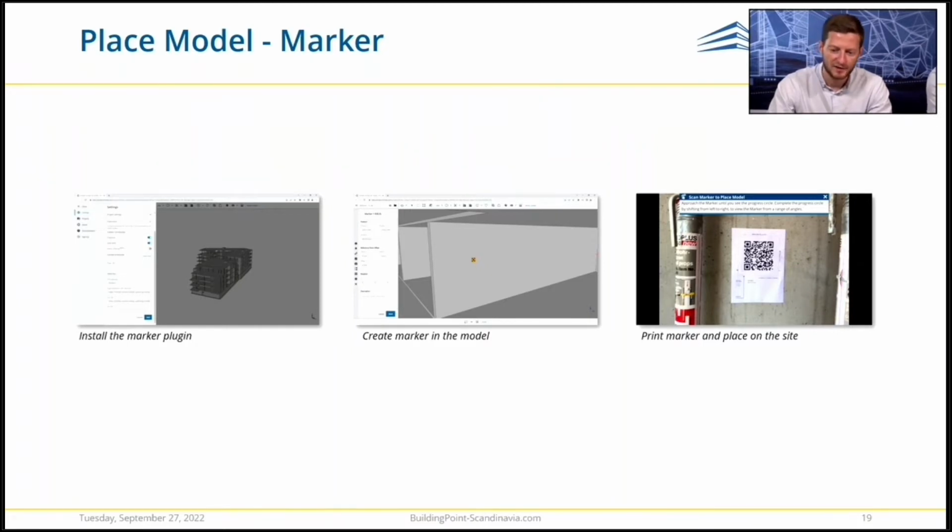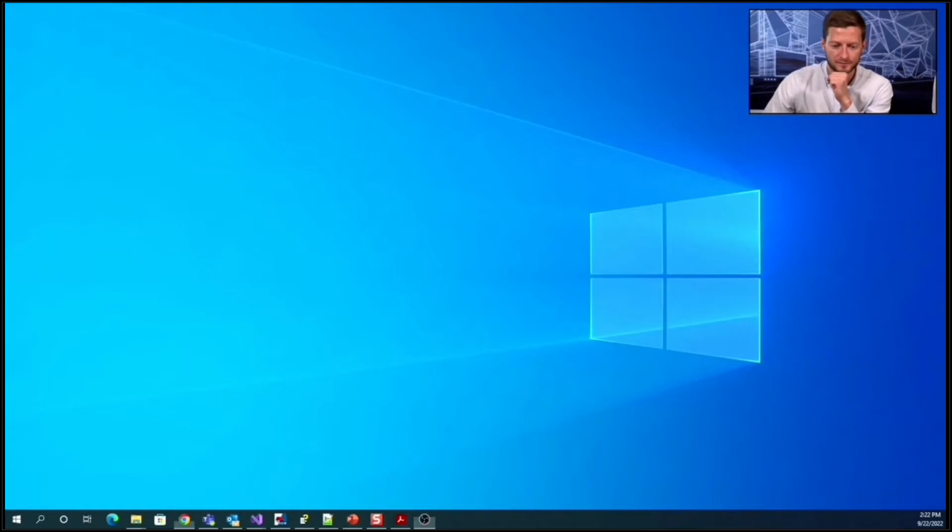The drift depends on the device you use, and of course, the more recent the device, the less drift should be expected, especially the newest devices with the LiDAR system should be really helpful, but it's not necessary. It's recommended. It's always better. The general guideline is to operate within 5 to 10 meters of a marker, so a marker placed every 10-15 meters should be sufficient. But as mentioned, it may differ depending on the device you have and the model. So how to install the marker?